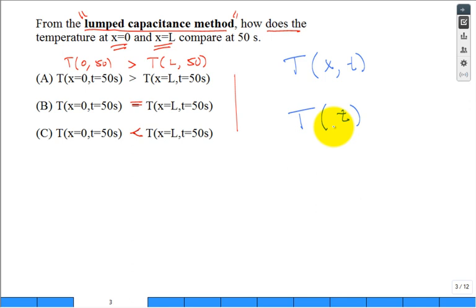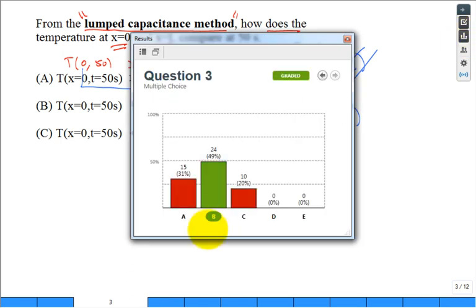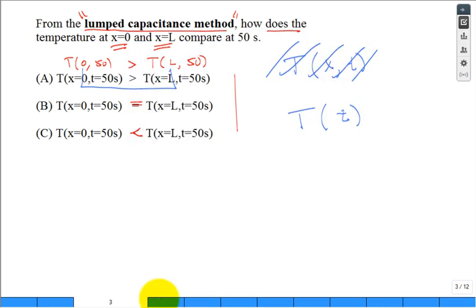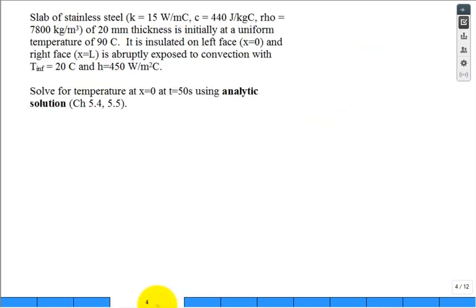B. He's learning. Right? So, can the lumped capacitance method discern between x equal to 0 and x equal to L? Just grade it. How come I don't have 100%? They're the same temperature. They cannot have a different prediction. It's not capable of predicting a temperature at the center versus the temperature at the edge being different. It would predict one average temperature, and it'd be a good average temperature for that slab. All right. Somebody says, not good enough.